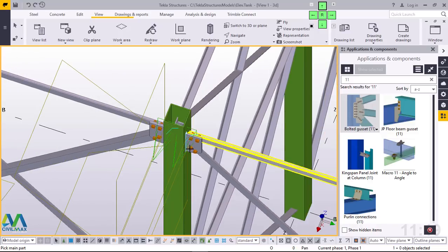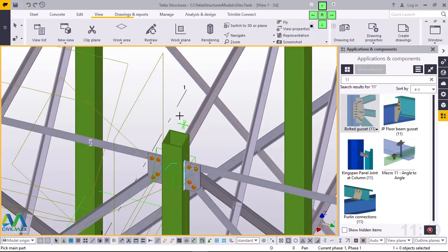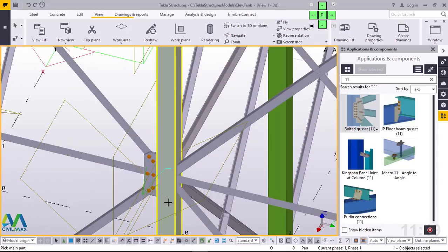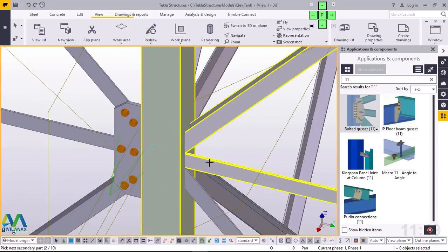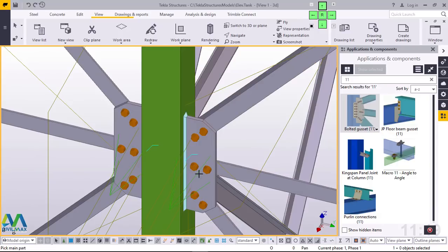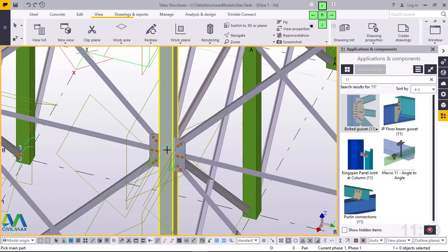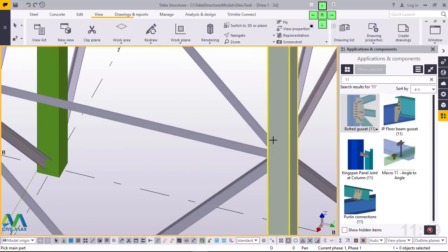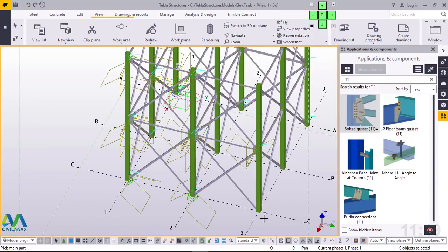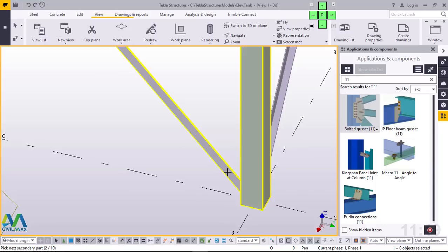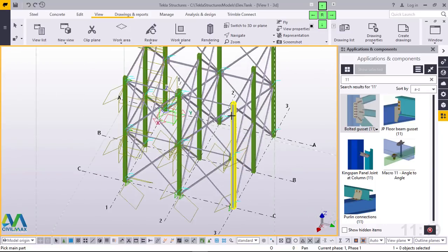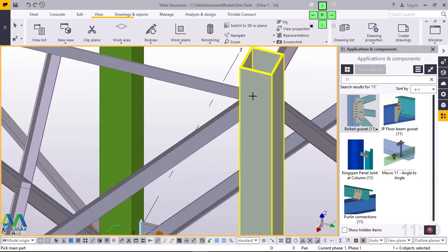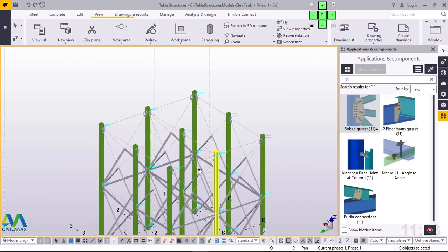Perfect. I'll turn that round by pressing Control, and I'll come at the bottom end here and connect these 3 braces. Once you've picked on the main, then pick on the parts that you want to brace to the column, and press the middle button on the mouse, and the connection will be created. I want to create connection between these braces. Let me create another one here, and press my middle button on the mouse, and the connection will be created automatically right away. Let me do the same. Done and neatly done.